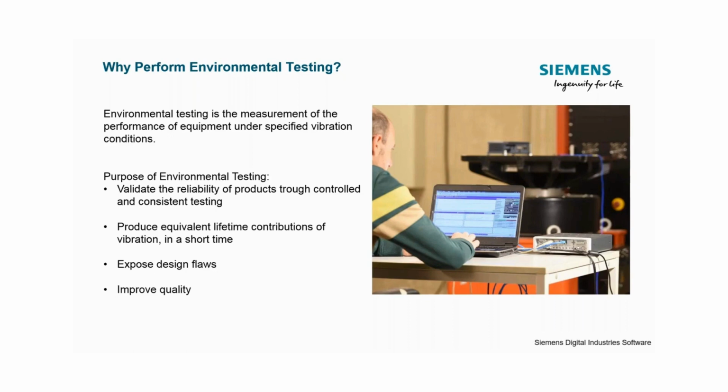If we're going to use an established standard, such as like a military standard, we have to ask, is this standard relevant to the type of operating condition that my part would actually experience? So we need to question these vibration profiles and question whether or not we're inducing the appropriate amount of vibration.